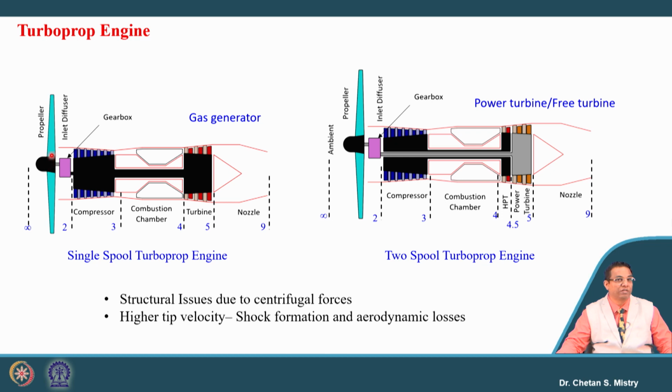Say this propeller is connected near the hub, and this is acting like a cantilever beam. Now because of the centrifugal force, there may be chances that it will have very high stress that will be focused near the hub, and during rotation it may come out. It is very dangerous. It will give a catastrophic failure.